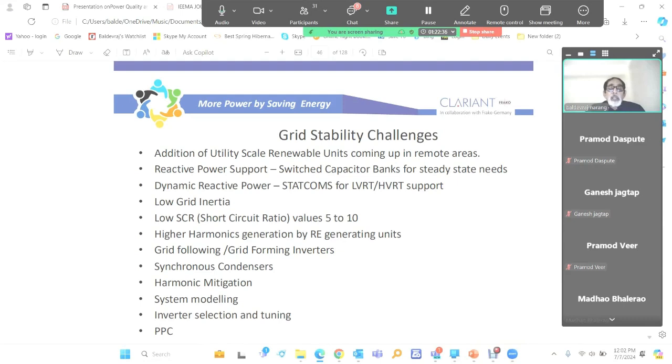So here we have to have a high pass filter, where we use another element called a resistor. That resistor is connected in a way that it absorbs all the higher order harmonics, and they are mitigated through the resistors basically. Those high pass filters are designed for mitigating the harmonics generated by renewable plants. And one good thing done by CEA is that they have mandated that all these plants, whether existing plants or incoming plants, have to meet the IEEE 519 norms of harmonics.